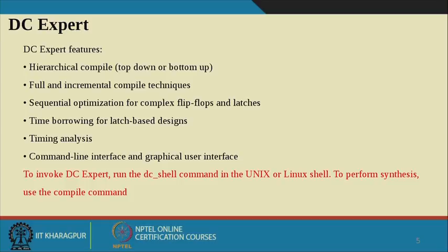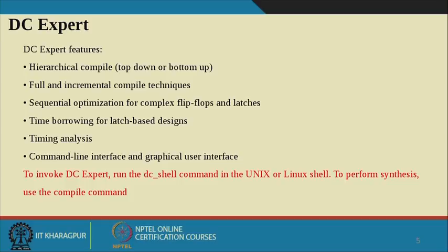Hierarchical compile mode means you can compile your design in two ways, either in a top down approach or in a bottom up approach. Okay. And this also provides full and incremental compile design. What incremental compilation and full compilation are will be covered in the VLSI physical design theoretical part. So here we are not talking in detail about these things, but they are supported in DC expert. That is a feature of DC expert.